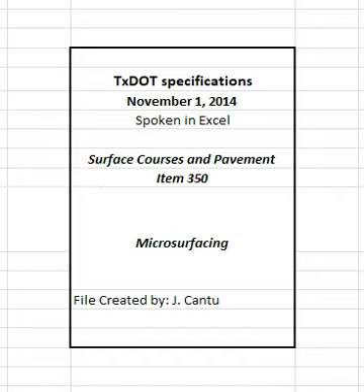Provide the engineer with approximately 40 pounds of each aggregate stockpile, at least 1 gal of asphalt emulsion, at least 1 gal of mineral filler, and sufficient quantities of any additives proposed for use. The engineer may accept an existing mixture design previously used on a department project, but the mixture design may be subjected to annual verification using laboratory-produced mixes before starting the paving season. Production may begin at the contractor's risk without receiving the results from the department's verification if approved by the engineer.